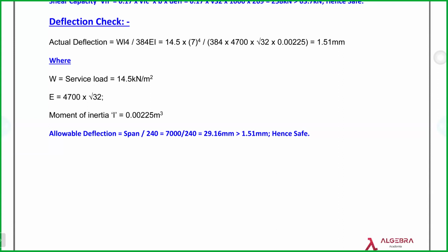It's very basic. Two-way slab, you do 4 layers. Bottom 2 layers, top 2 layers. Correct. Bottom you call it B1, B2, top you call it T1, T2. Doesn't matter. Which direction of the reinforcement am I going to lay first? So many slabs we have seen, they break into pieces. So many buildings we have seen, because of this blunder mistake, the slab has got directly cut.